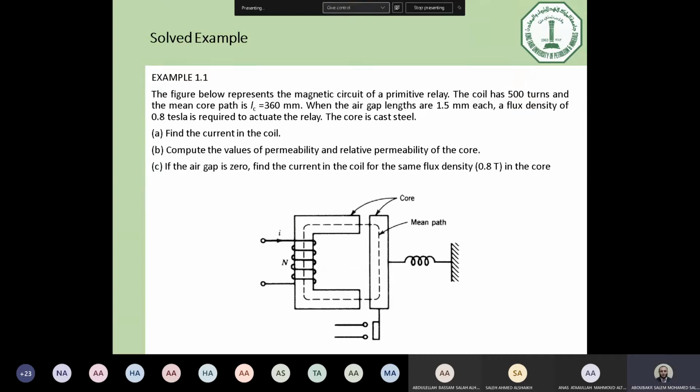Guys, why do we use a relay or contactor instead of the switches, if the only function we need is on and off? Is it so we can control it using electricity? Exactly, it's for the matter of control and also for the matter of protection. So relays and contactors are mainly used in protection and control. However, the manual switch, you cannot use it in control or protection. And if the current moving in the circuit of the switch is higher than the rating of the manual switch itself, the manual switch will not be interrupted. It will be damaged.